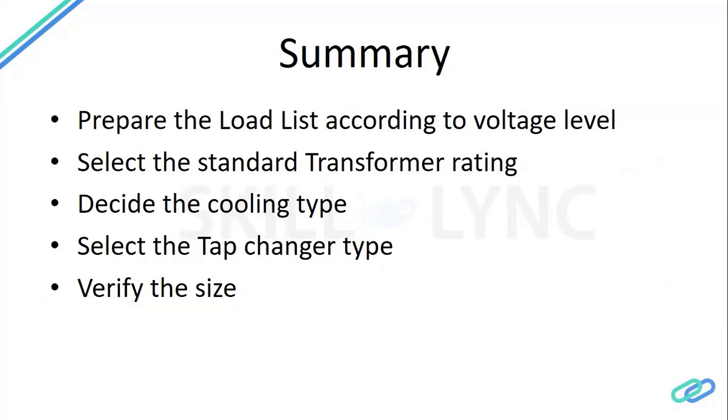Now we will summarize what we have seen till now on transformer sizing. So the first step will always be to prepare the load list according to the voltage level. What is the voltage level you have selected? You have to prepare the load list, and then do the calculation and select the transformer rating.